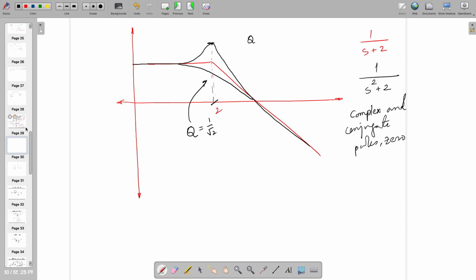So although you didn't want to amplify the signal with just an inductor and capacitor in series or parallel, at the position where you get the highest amplitude, it will give you V out higher than V in. This is what you can see here in the plot. The magnitude plot is V out divided by V in.